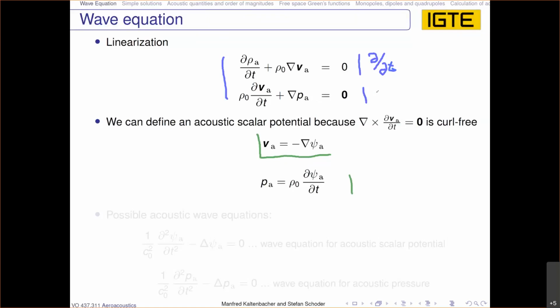So when you now apply the divergence operator, which is always nabla dot, then you also have here, a dot is missing here. Sorry, there should be a dot. The nabla operator is working as a scalar product on the particle velocity. Then we see when we subtract these two, we get an equation for the acoustic pressure and the acoustic density.